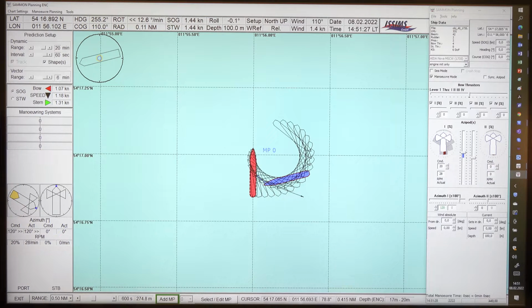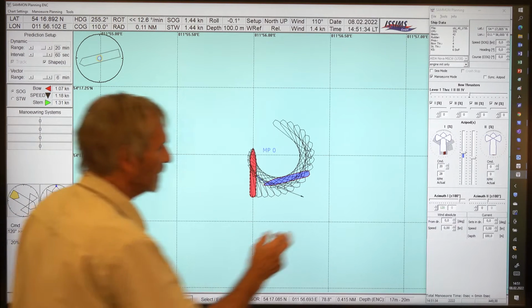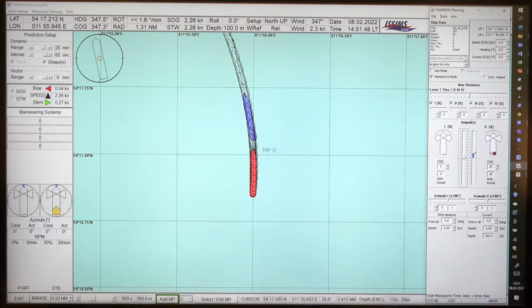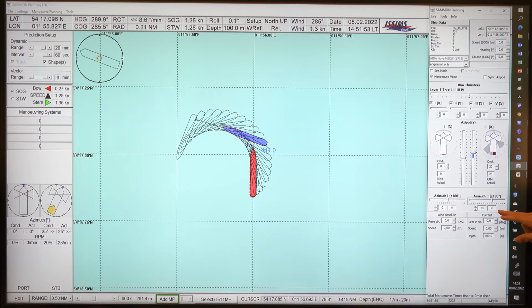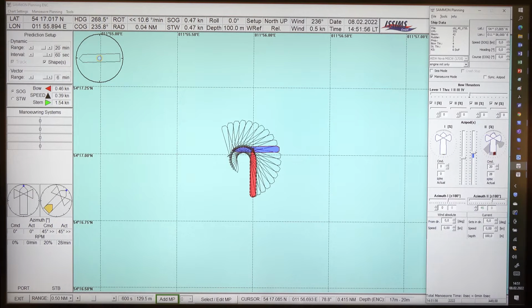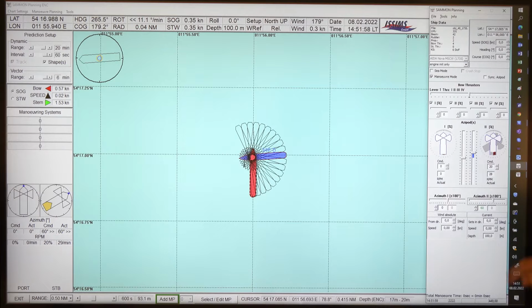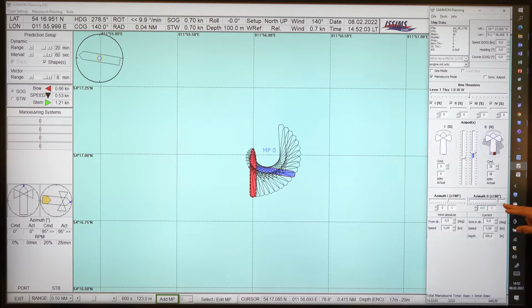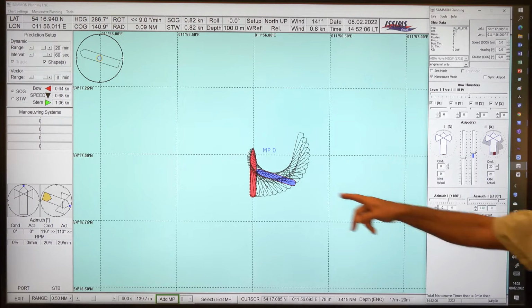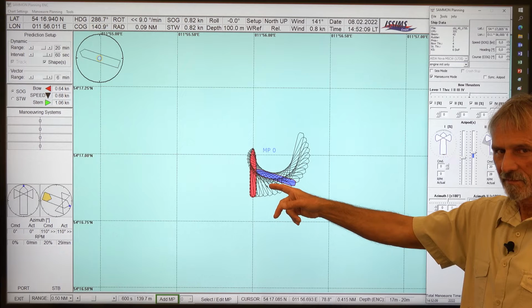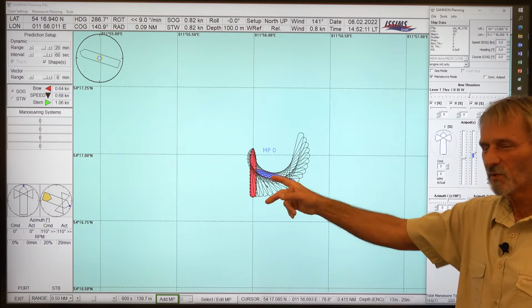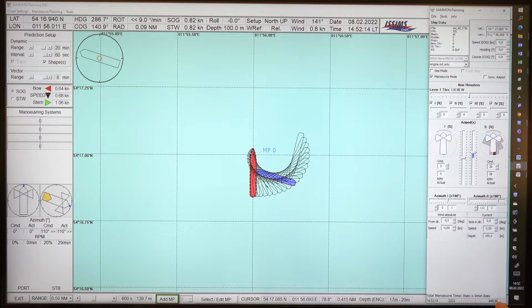Normally we could also use this pod for smaller angles. So if I switch that to 0, then it's the same as on the other side. If I'm using this pod now, it works in the same way as before. Even for the 60 degrees, it looks like this. But if we go for a tougher configuration, then we see the force is not the same magnitude as we had before. So the ship is not reacting properly to the same angle of the pod.